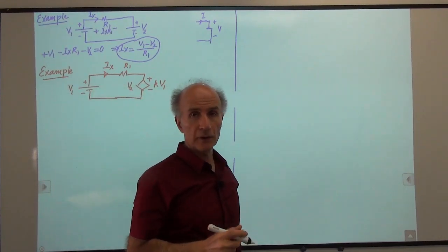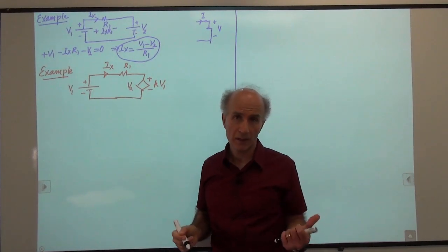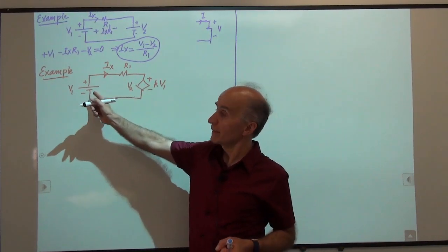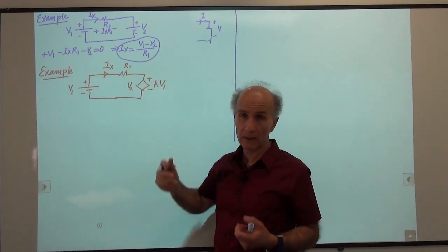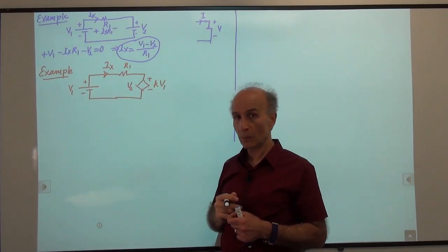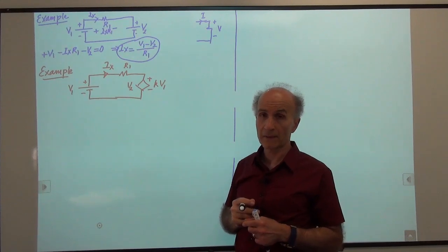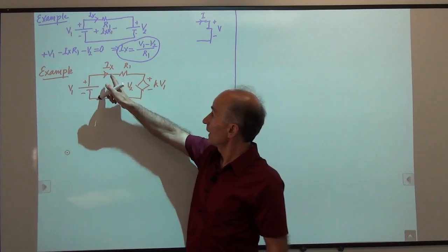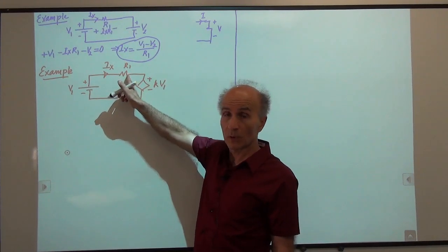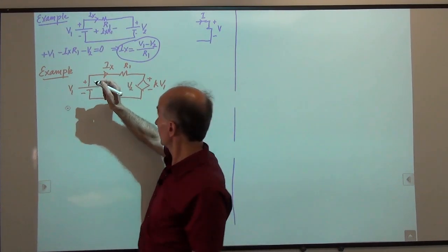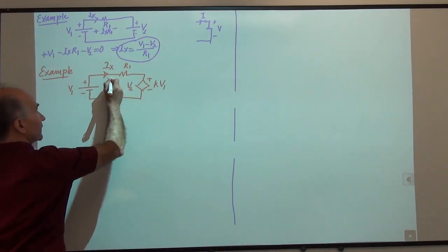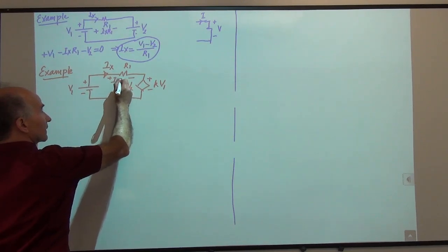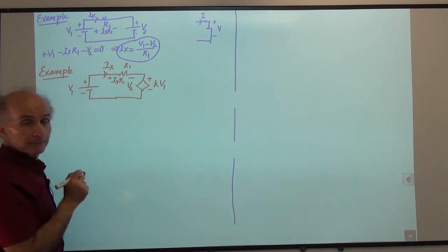All right? So the resistor is known. V1 is a constant voltage like a battery. And this V2 just copies this voltage and multiplies it by K. K can be any number we want. So we would like to see how much Ix is. All right, not a problem. So again, we follow the same procedure. We say this current flowing through this resistor will give us a voltage, and that voltage will have its higher end here and lower end here, and its value is Ix times R1, just like before.